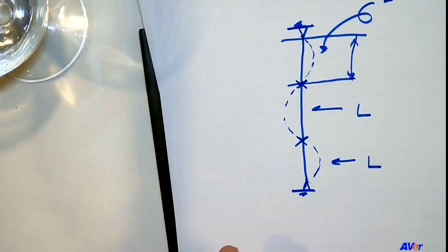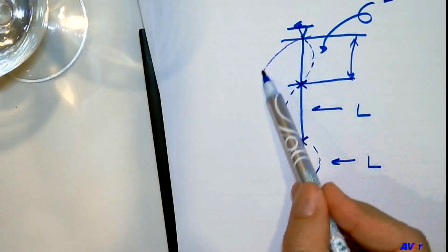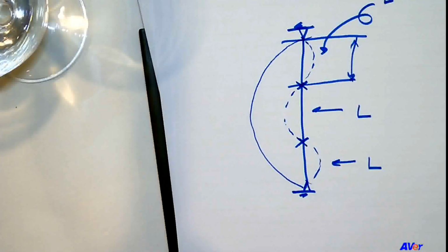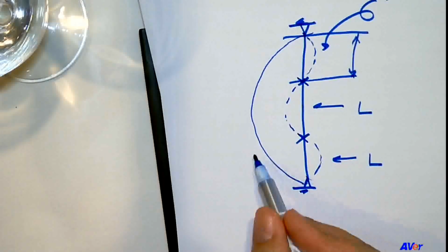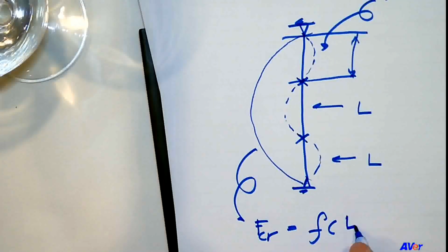So in that case, my F critical will become Fy, right? But in this case, if I don't do anything, it is free to move like this. That becomes my unbraced length. And therefore, the F critical will depend on that, because F critical is a function of L over R and Fy.